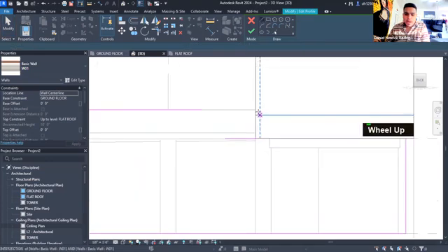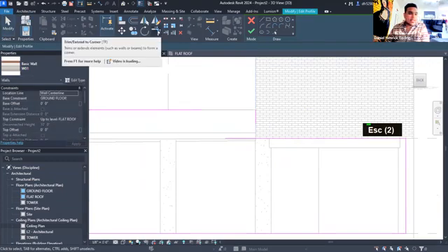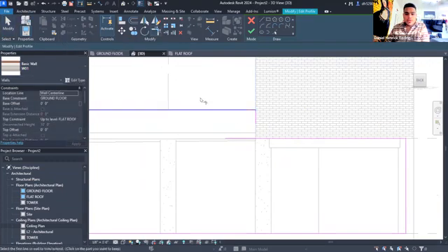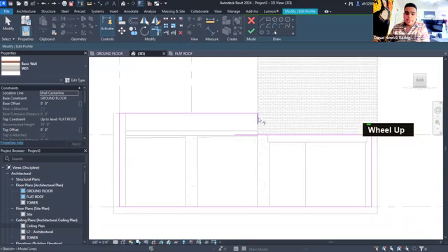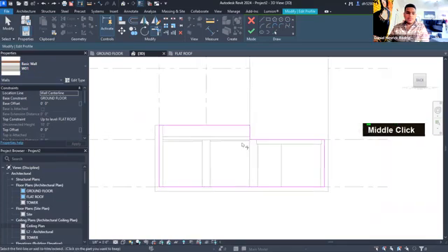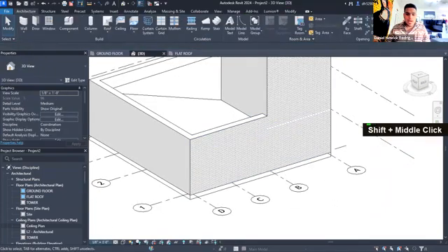I'm going to hit the line tool here and create a line going down. And now this very, very useful tool here, the trim/extend corner. I'm going to use this tool to make this line and then this line connect. There we go. Look at that. Quick tip, the trim extend tool, it works on the side of the line you connect. So I'm trying to make a corner from this line to this one. If I click on this side, it's going to corner to this side. If I click here, it's going to do that. Okay. So do this. Once you're done with that, you're just going to hit the check mark there. And if we look in 3D, now we're all good to go.